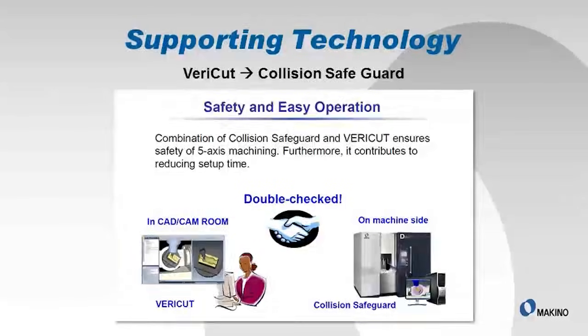One of the challenges when you get into doing 5-axis is the fact that we are now adding on 2 additional axes, and we can be either moving the spindle around the part, or we can actually be moving the part around inside of the machine envelope. What this does is it gives us additional things to consider for collisions. So one of the things that we would recommend is always having a collision software to check for these components. One of these is called Vericut.